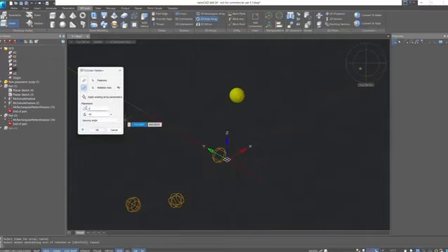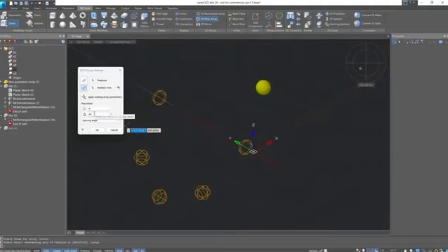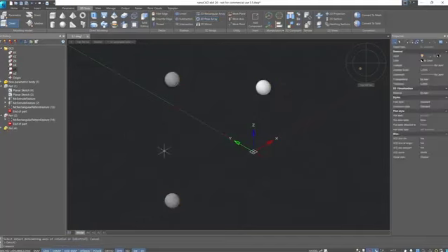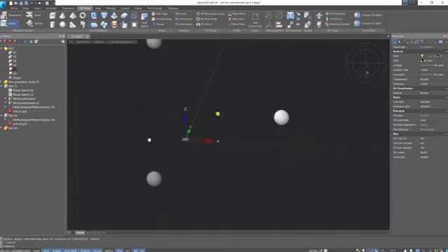Below, specify the required number of elements. Set it to 6 and the angle. In the Angle Selection option, we can specify the filling angle, and the chosen number of elements will be arranged in the specified range, say to 170 degrees. Or we can choose spacing angle. For instance, let's keep 3 bodies and set the angle step to 120 degrees. As we can see, we've created an array of 3D bodies around the Y-axis, and the angle step between them is 120 degrees.